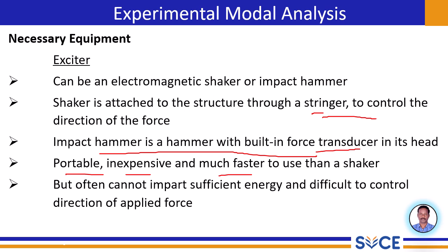However, there are limitations. Impact hammers often cannot impart sufficient energy to effectively excite all the modes of a very large or heavily damped structure. Additionally, it is difficult to control the direction of the applied force precisely. The input force is an impulse, which may not be ideal for isolating specific frequencies as effectively as a shaker.